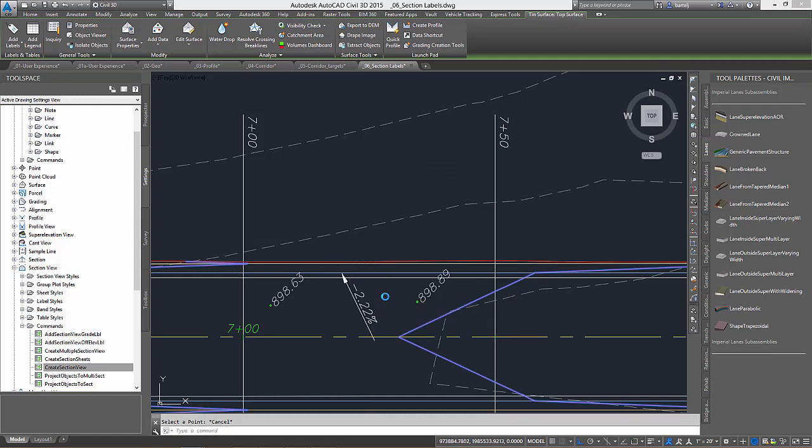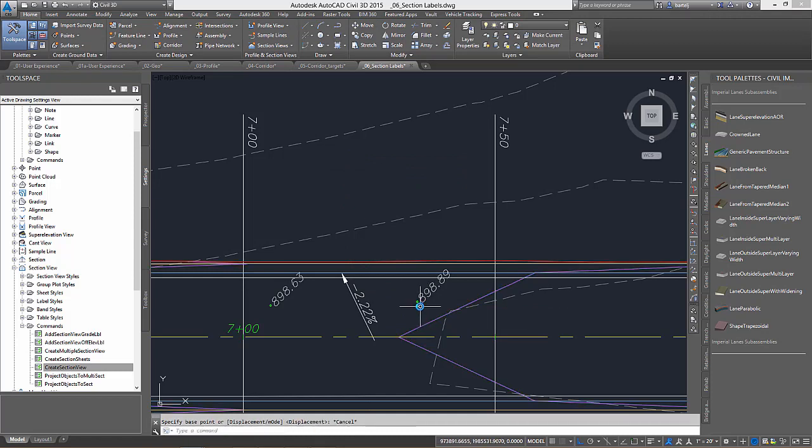So let's try this. We're going to copy these objects here from this point out to here. And when I drop them, they do exactly what we would expect. They turn into question marks because it doesn't know what to display, because the object isn't out there. All right, historically, that would have been a problem for us. We would be forced to recreate that annotation to be able to use it with other objects or associate it with other Civil 3D components.